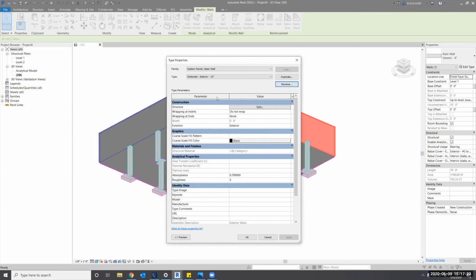The naming of walls is very, very important. We're dealing with a simple little structure back here, but when you're dealing with a large podium with many different types of walls that are cast in place or shotcrete, that information is very important to know, because that tells a concrete subcontractor what he's allowed to do, how he's allowed to either shoot that wall or if he has to cast that wall, okay?